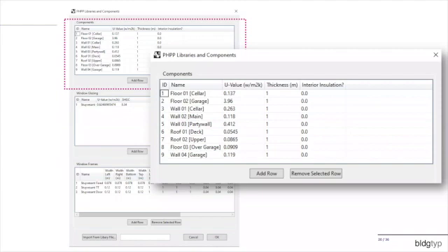This is one place where I know we need to build out the tool with a little bit more robustness. Obviously here it's quite simplified. This is very similar to maybe the components worksheet in the PHPP. So all you have here is the ability to enter a total U value or a total thickness. This is different than the assembly constructors that we have inside of PHPP. In our office, we don't use those assembly constructors. We do all of our assembly U-value calculations in Flixo. We do a graphical method for doing those calculations.